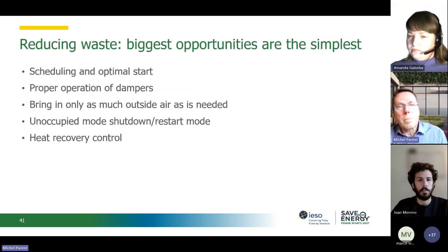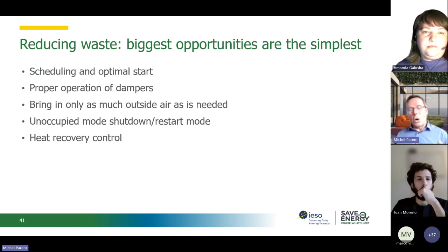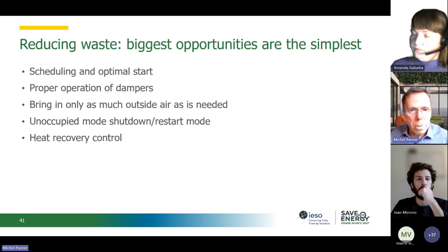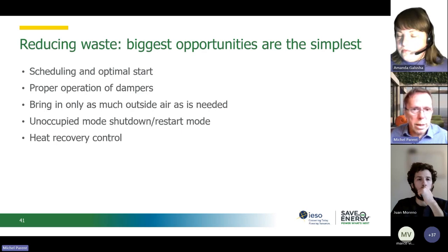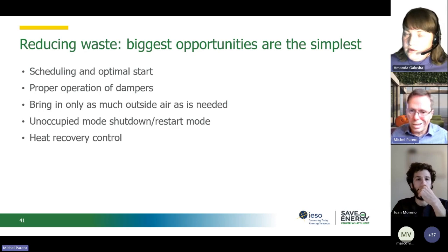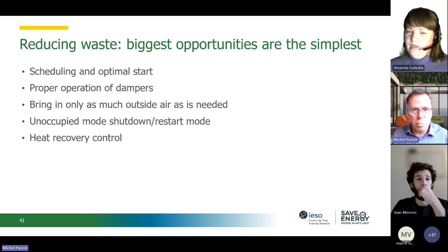The first thing you have to look at, and when we do a recommissioning, the first thing we always find is reducing waste. It's amazing how many systems, even though they're run on schedule, are not running on an optimal schedule. Some people will start their makeup air unit 3 hours before occupancy, and I always ask why. They say, well, it's cold outside, I've got to start the system early. Well, you're just shooting yourself in the foot, because a makeup air unit is not a heating system. It's purely ventilation. Start that system half an hour or 15 minutes before actual occupancy.